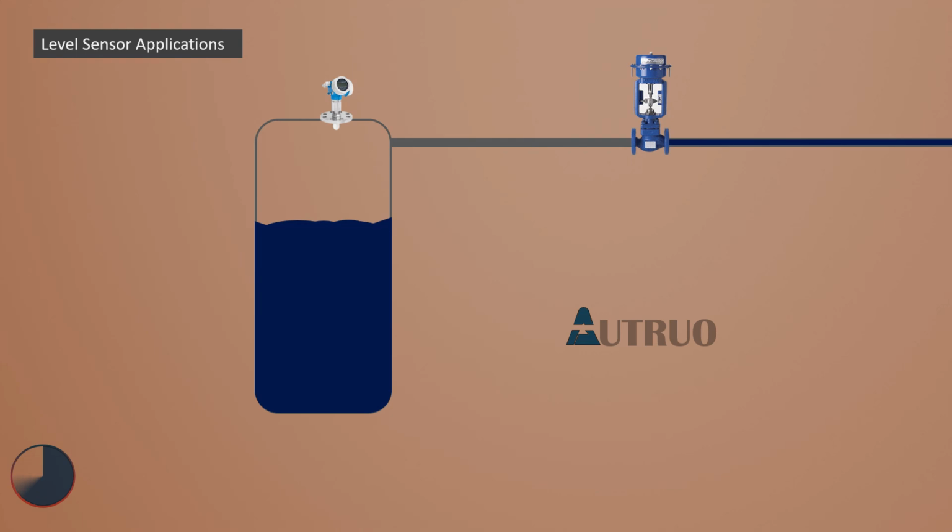In an ideal process setup that requires constant availability of water within a certain range, the level sensor is the go-to device. This instrument is usually used to open and close the product inlet valve in respect to the varying liquid level. It acts as an interlock.